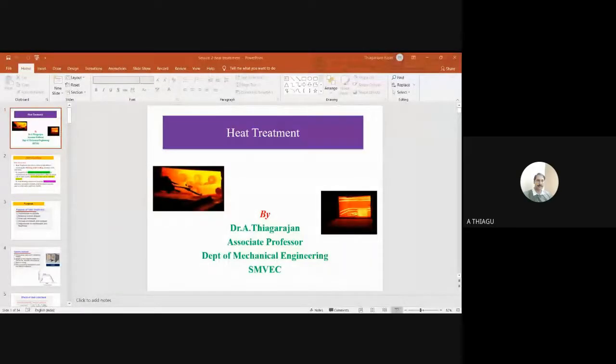So I will show the temperature. You can look at some applications of recrystallization, where entire steel metals are modified. This is a rectangular beam. In this heat treatment process, the cold worked steel is heated to a temperature above the recrystallization temperature, and the material produces a new structure, in the form of new grains that are developed.